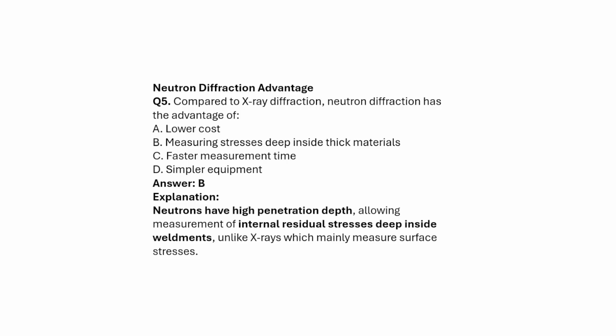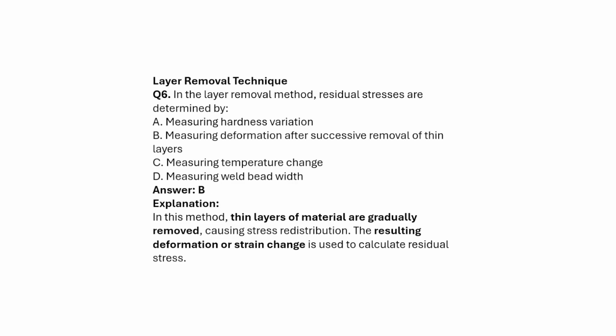Okay. Compared to X-ray diffraction, neutron diffraction has the advantage of: low cost, measuring stress deep inside the thick plate, faster measurement time, or simplest equipment. XRD can only measure the surface stresses. Neutrons have a high penetration depth, which allows measuring the internal residual stresses deep inside the weld metal, unlike XRD, which measures the surface stresses.